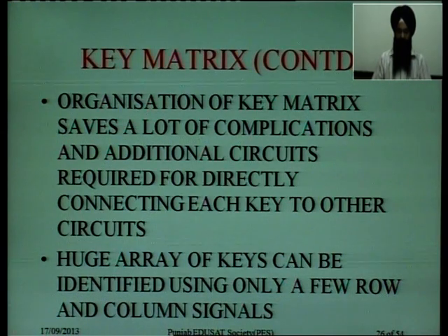Here when there are 101 keys or 104 keys, there is a huge array of keys, and one key is pressed first, then another, and we have to detect which key is pressed, and then convert that key signal into a hexadecimal code, and then send it as input to the computer machine. So it requires very fast processing.